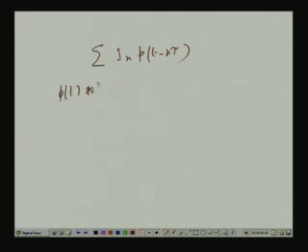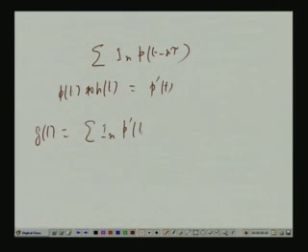So that means what you transmit is the sum of I(n) p(t - n tau). The problem is these pulses pass through the channel, and the channel is not ideal. So, p(t) convolved with the channel will give rise to some p'(t), and this p'(t) will no longer satisfy the zero forcing condition. So, obviously, what I will receive is, say, g(t) as the sum of I(n) p'(t - n tau).